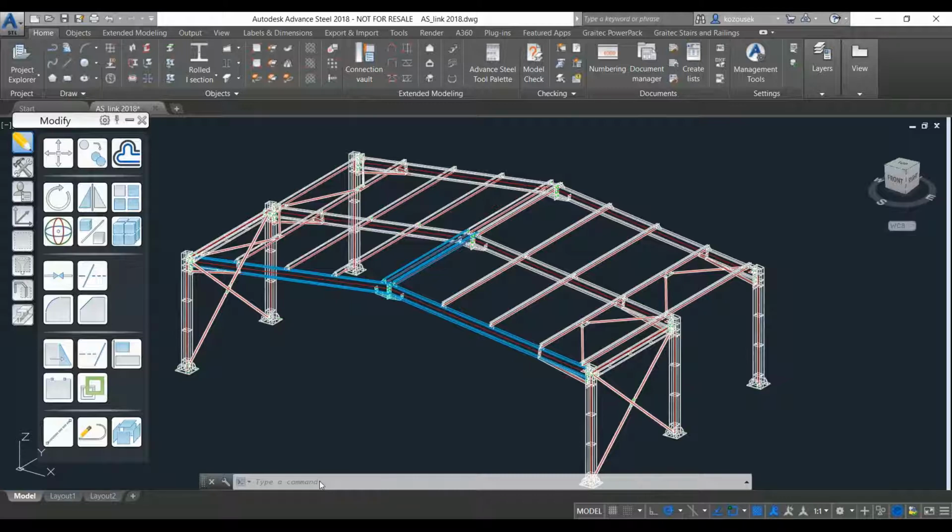And this we type in, and it asks us to select the node of the joint and select members of the joint that we have 4 here. And this truss roof joint, and we select the items like plates, bolts, and welds. And now this joint is being exported to IDEA StatiCa, which opens immediately. And here we can see the joint imported.